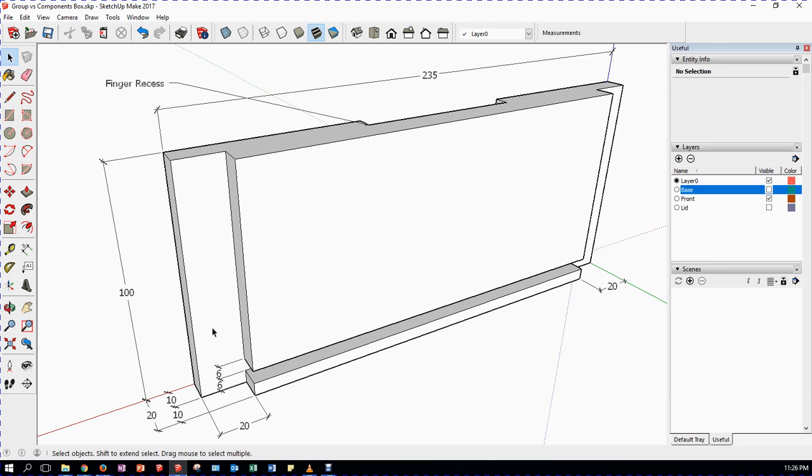There's only one problem: how do I then go back to showing the rest of the box? Well, I took away the layers for the dimensions, so I'm going to add another layer here called Z front. Lots of history about why I use the letter Z as my first letter for these, but the Z underscore tells me that this is a layer that contains dimensions. So I'm going to take all of these dimensions that I have here.